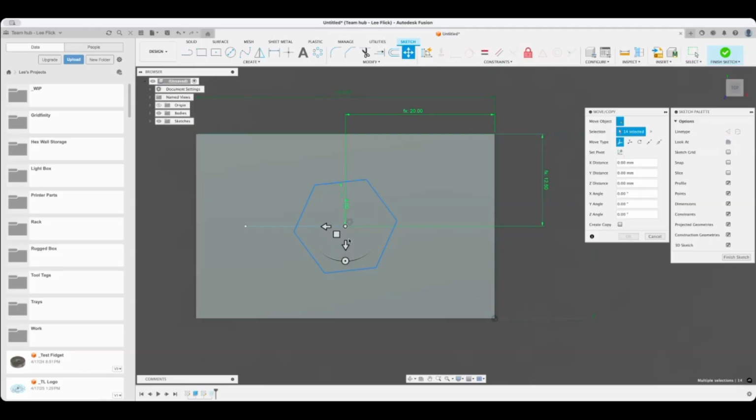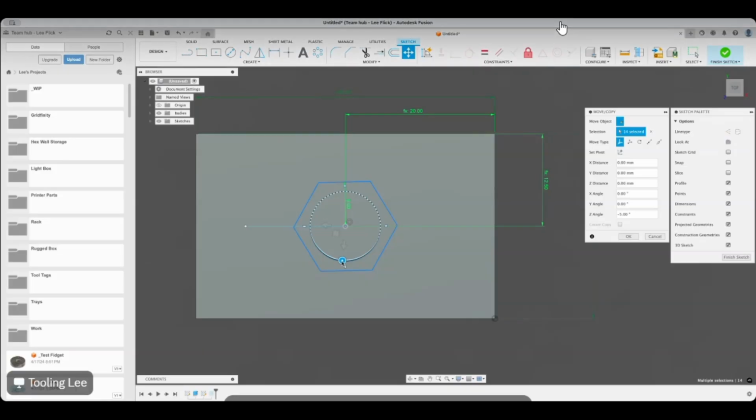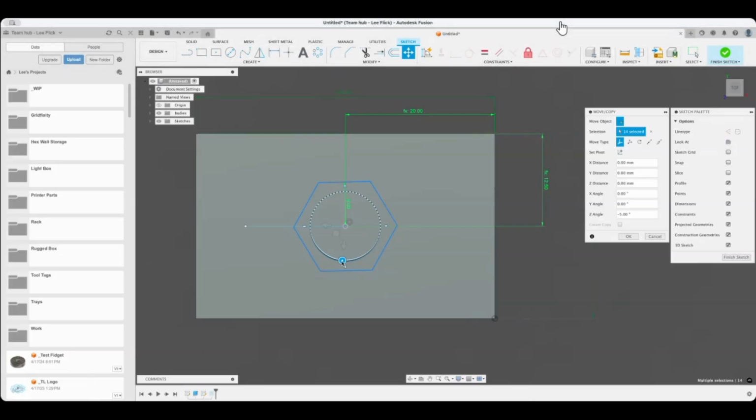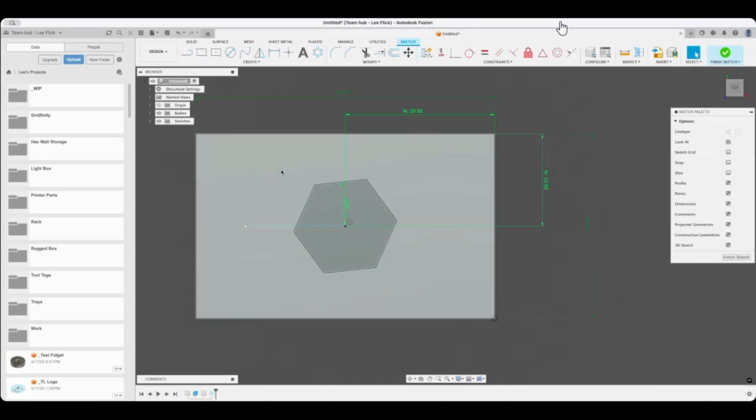So it's automatically in center now because I put that line in, and I can rotate it. Now it won't parallel constraint, but I can move. If you could coincident the vertex of the hexagon with the straight line, or parallel the top edge of the hexagon with the edge of the box above.